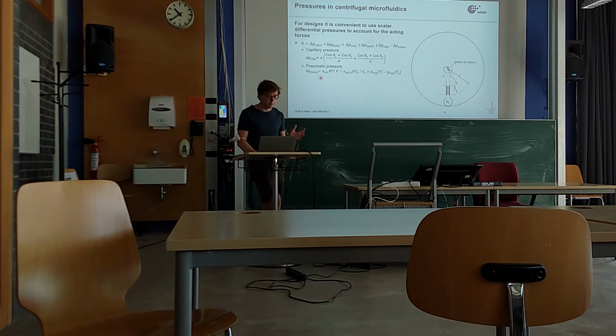So the idea of this pneumatic pressure is, on the left-hand side, you can see that it's based on an ideal gas. So this is nothing else than the ideal gas law that you learned in the first lecture with Niklas. And it's also depending on the vapor pressure. So if you think about it, if you have a small liquid volume, you heat it up, let's say it's water, you heat up to 100 degrees, you have evaporation, and obviously evaporation generates a pressure that can become very important in microfluidic settings.